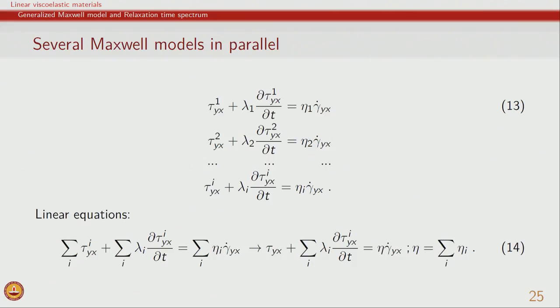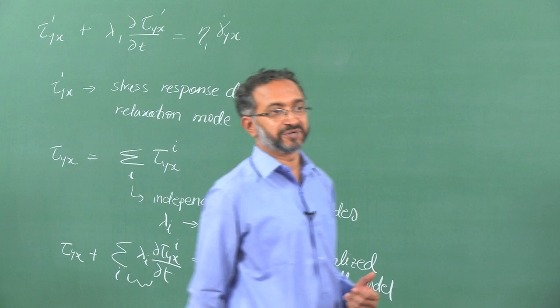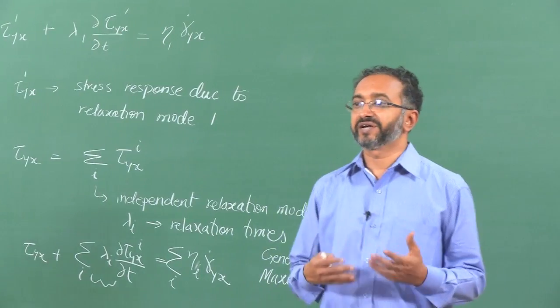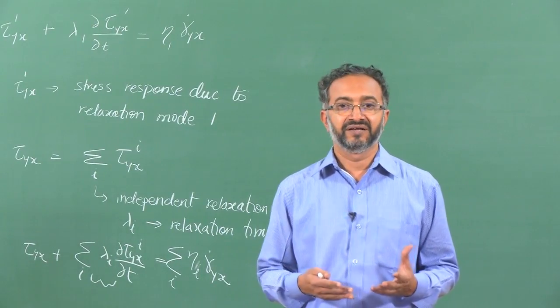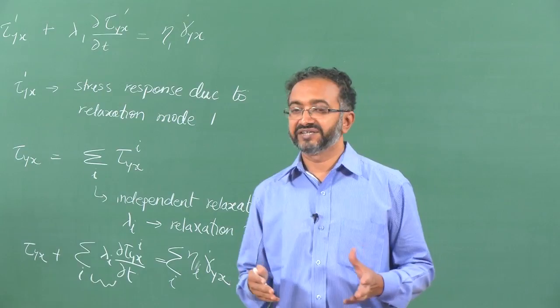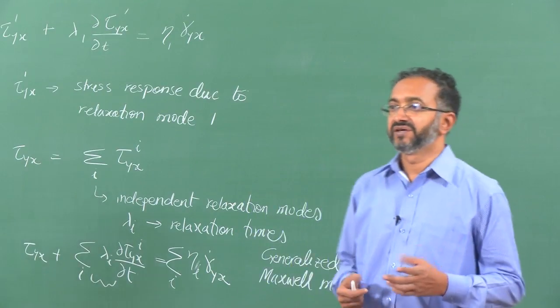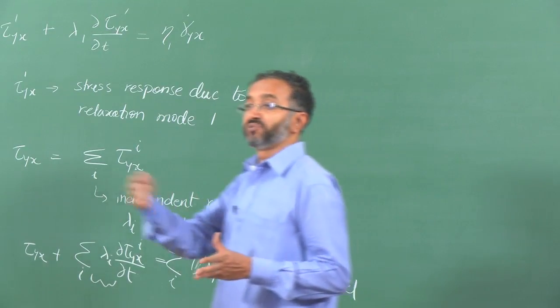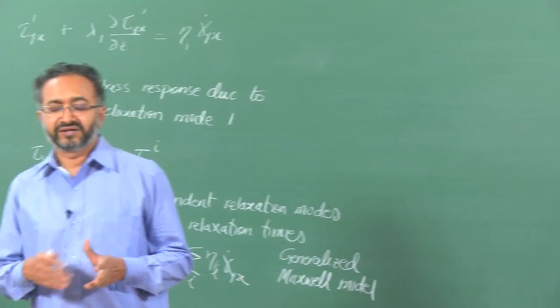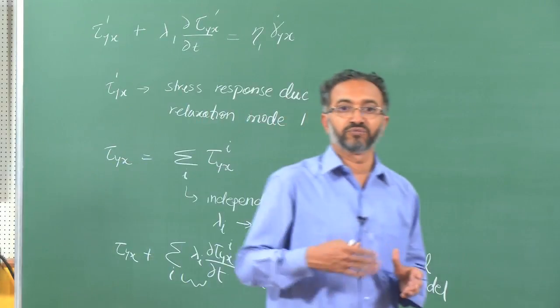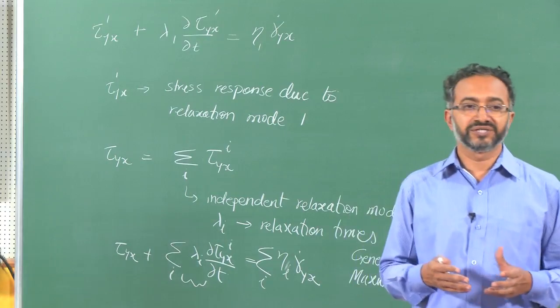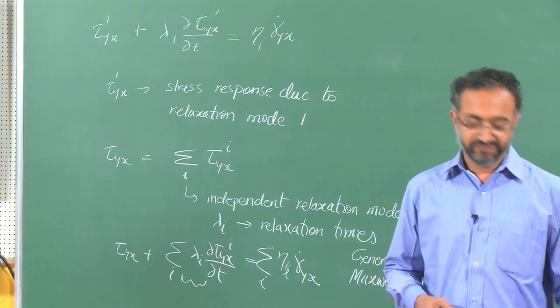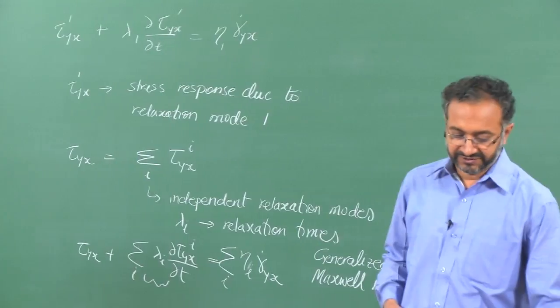So, using this modeling of such kind, you can then attempt to describe and estimate the relaxation time spectrum in a material. So, when you get a G prime, G double prime for a given material, you can then characterize it, and that is what we saw last time using some of the 10 mode relaxation model, 10 mode Maxwell model or a 4 mode model. So, those can be used to describe any complicated variation of material properties.